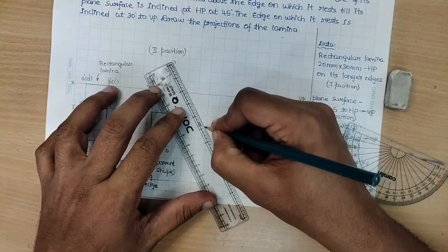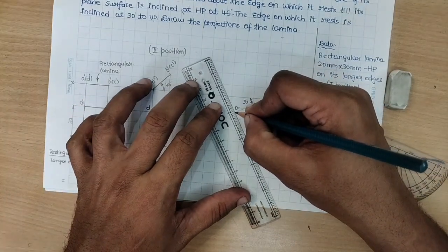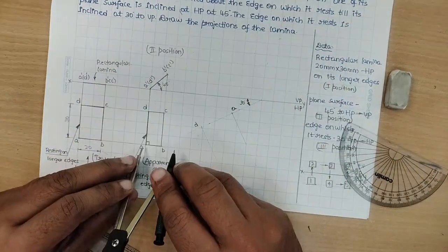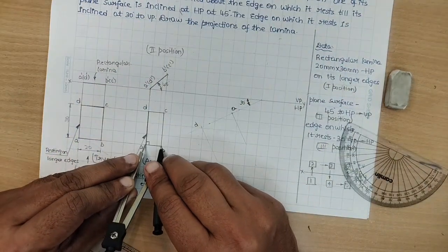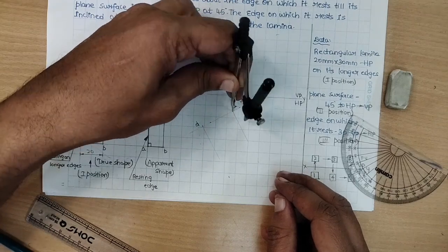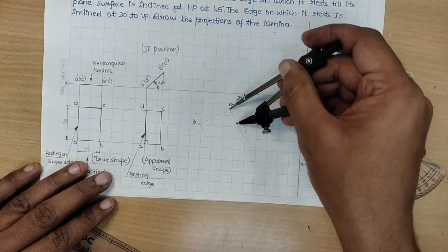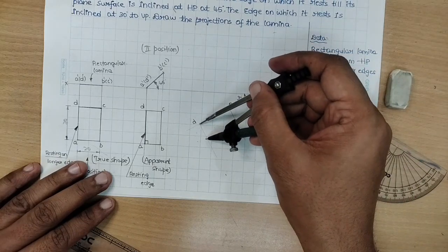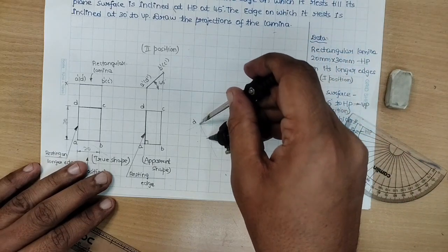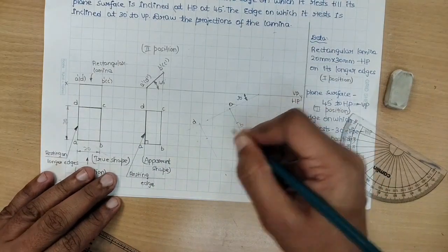From the point D, draw one 90 degree line. Also from the point A, draw one 90 degree line. Check out the distance from A to B. A as the center, cut an arc on the 90 degree line what we have drawn. I repeat, A as the center, transfer the point. Similarly, D as the center, transfer the point to get the point C. This would be the point B and the C.